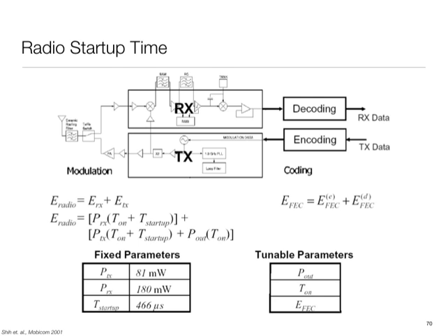Interference and multipath. Okay, so interference and multipath in what manner? You get more interference, there is more multipath, so you need more transmit power. Okay, so I need to send at a higher power than pure distance would have justified. Okay, so that's one. What else?